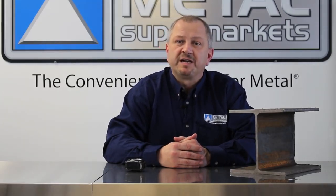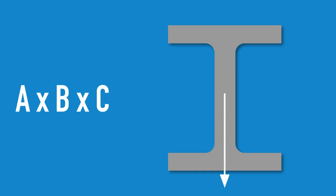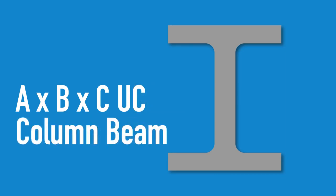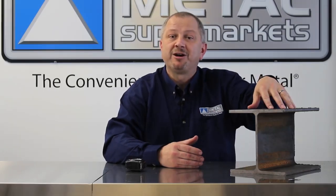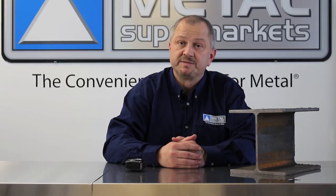For our friends in the UK, beams are measured differently, using metric measurements. They are identified using a code that consists of depth, the flange width, the weight in kilograms per meter, and either UB or UC, indicating if the beam is universal beam or column beam. So, in the UK, our beam here would be a 203 millimeter by 203 millimeter by 46 kilograms.